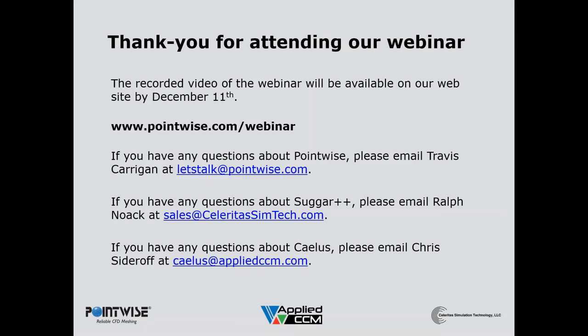So GGI, which I kind of alluded to, stands for General Grid Interface, and that is available in another variant of OpenFOAM called Foam Extend. So it's effectively a way to do these sliding interfaces I was talking about, doing prescribed motion cases where you have a rotating zone and a stationary zone, and the way that can be handled is with this sliding interface called a GGI, or in the vanilla OpenFOAM it's called AMI, Arbitrary Mesh Interface.